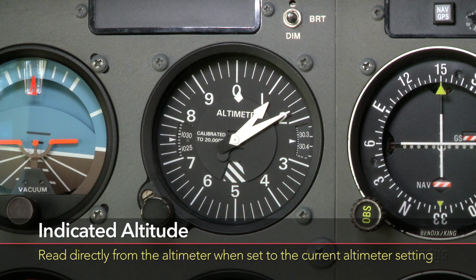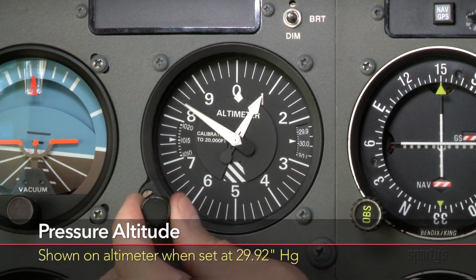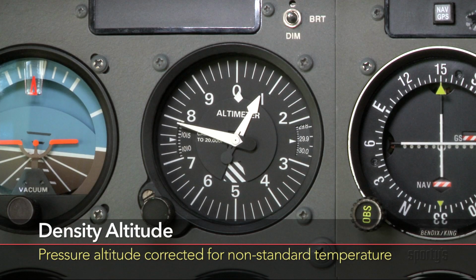Indicated altitude is read directly off the altimeter when it is set to the current altimeter setting. Indicated altitude is the approximate height above mean sea level, abbreviated MSL. Pressure altitude is read when the altimeter is set to 29.92. Pressure altitude is used to solve calculator problems of true airspeed and density altitude. Density altitude is pressure altitude corrected for non-standard temperature.